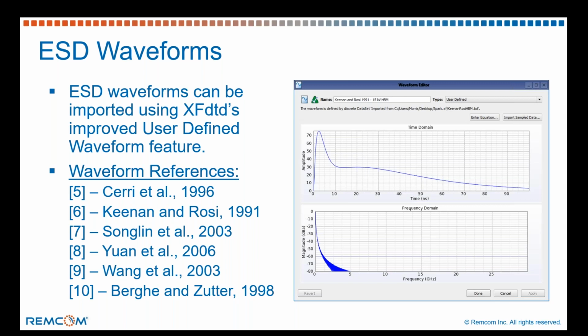The ESD standards' target audience is more, you could say, the hardware designer or the ESD gun manufacturer. And so what you often find in the standards is that they describe the electronic circuits, but they do not give analytical expressions for the ESD waveforms. So there's a whole body of work to determine analytical expressions for ESD waveforms, and that's what we're using here.